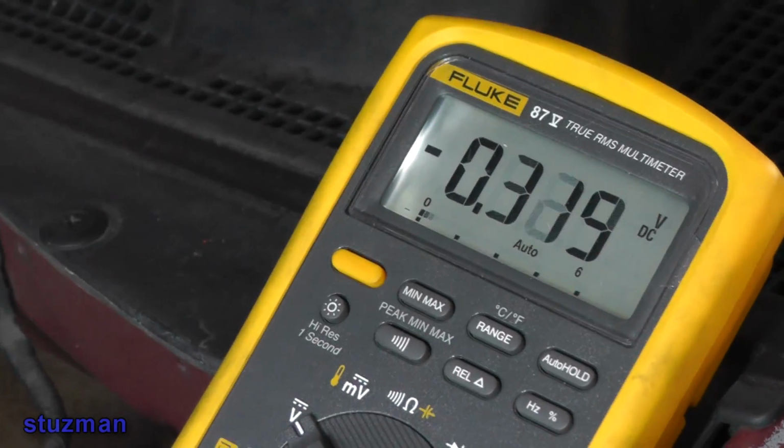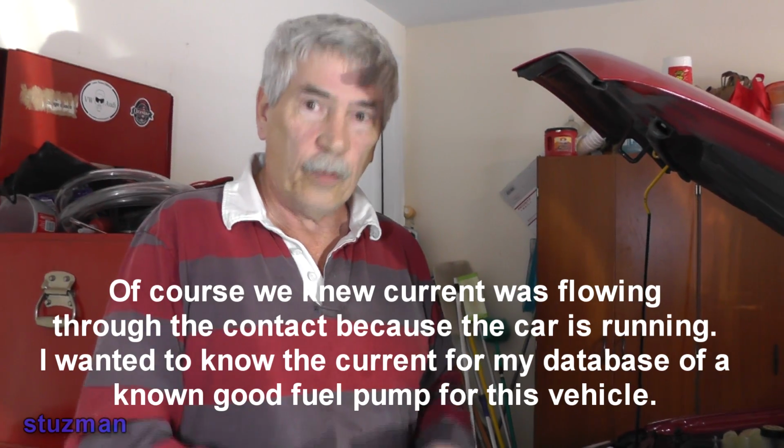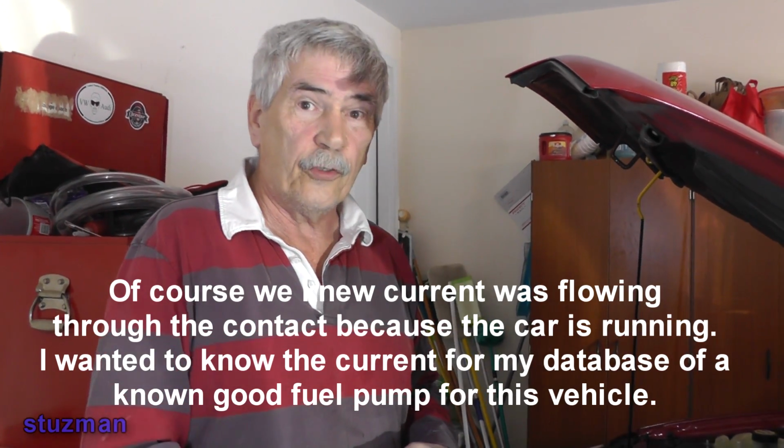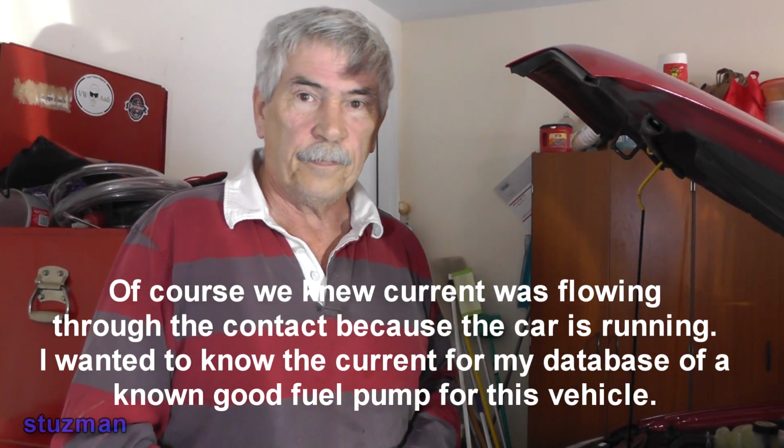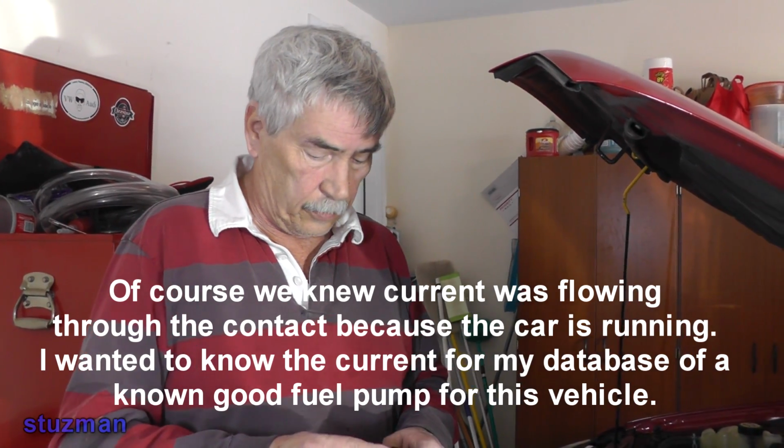Cool. Okay. When you're doing these tests, like when you want to check a relay contact like I was just showing, or if you want to check a switch or pressure switch or any kind of switch, it doesn't matter. Anything that has contacts, you can do the same method. However, you've got to make sure that you have current going through that switch or relay contact or whatever you're checking. That's why we checked our current first. We wanted to make sure that we had current going through this relay contact. So just make sure you've got current coming through your load.